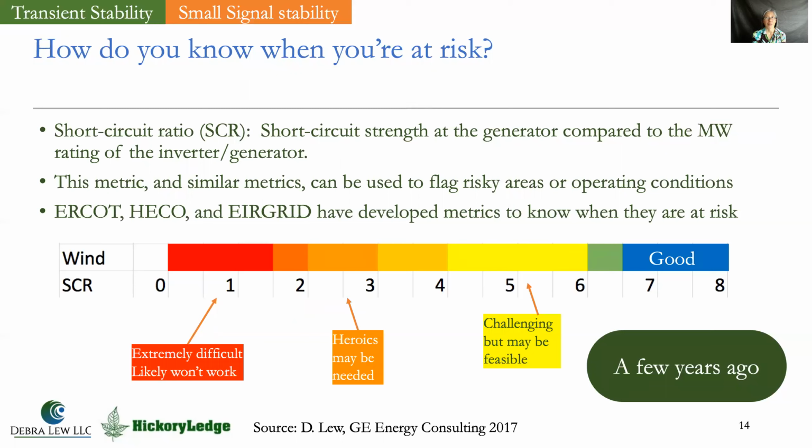You'll recall, we said this in the last tutorial, that inverters basically read the voltage and frequency on the grid. They need a strong signal to be able to read, so they can lock into that with a phase locked loop, sync up to that, and then inject current that matches that. Basically when that signal gets too low, they can't lock into that stably. So they've got to have a strong enough grid to lock in and stably operate.